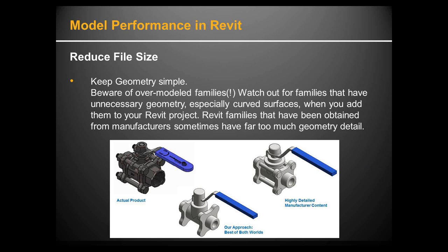Yeah, my example on that is working on a large-ish hospital that had several files, in the CD phase, probably beginning of CDs. Had a parking garage, had the hospital, had the bed wing, different files, had interior, core and shell, had structural, had MEP, had low voltage. And Revit was okay. It was moving a little slow, but tolerable. And then we got the file from the kitchen designers, kitchen and dining room. It was just a few hundred square feet compared to a 500,000 square feet building, a really small piece of the building. Revit was instantly twice as slow just by linking in that one file.